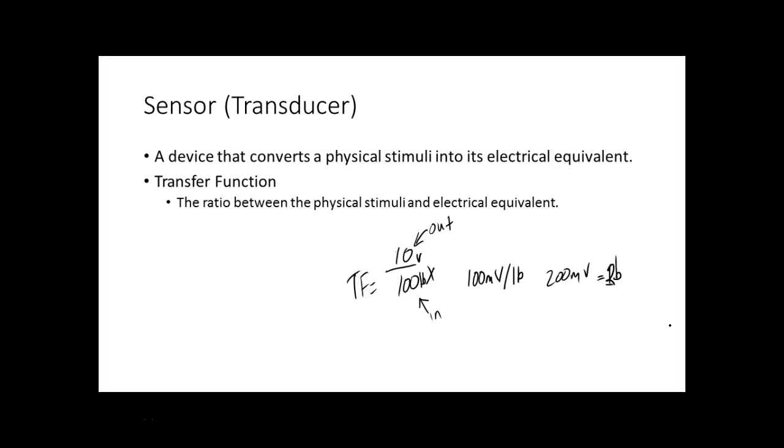speedometer uses. Car speedometers used to use a magnetic spinning wheel, and they'd put one inside the other and spin the outside. So you actually had a flexible metal rod coming up to your speedometer, spinning around. And the speedometer had a spring on it, and depending on how fast the outside would spin, it would depend on how far the needle went up there. But we don't do that now. How does a car speedometer work? Well, it works off of voltage, right?